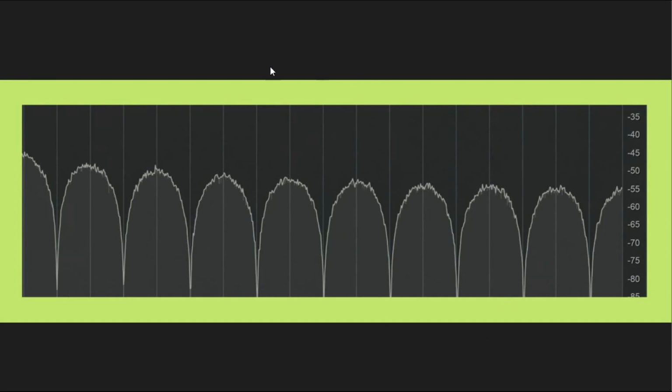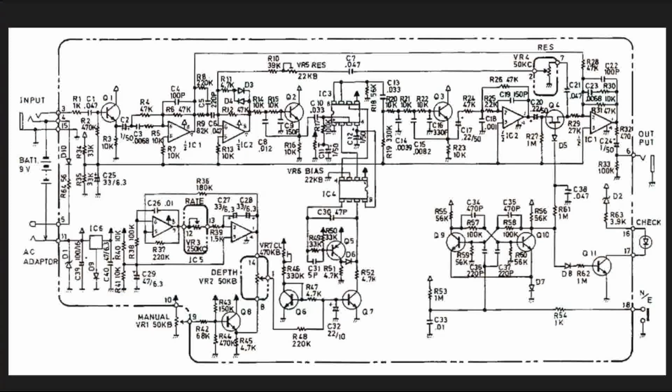Okay, but this is what's called comb filtering. It's just a whole series of notches, and it gives it that weird, if you will, sound that those types of modulation result in. So that's where our biggest difference is. Very short amount of delay time through here that we're modulating is causing those notches in the frequency response so that we get that comb filtering.